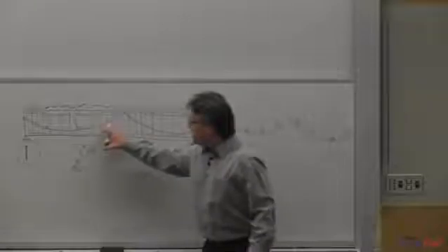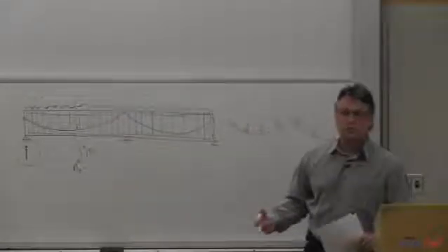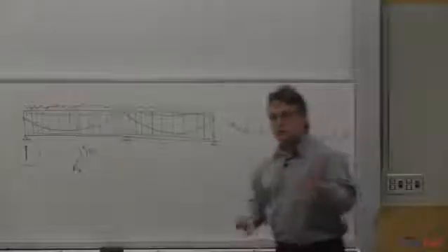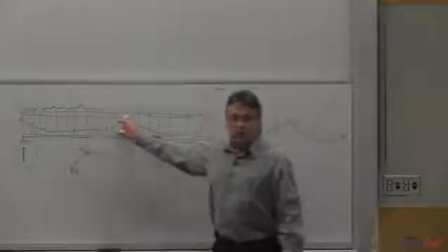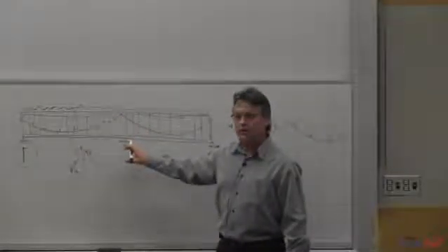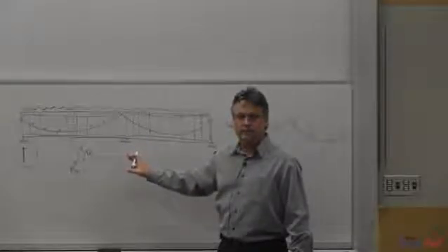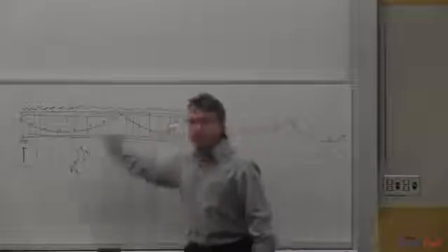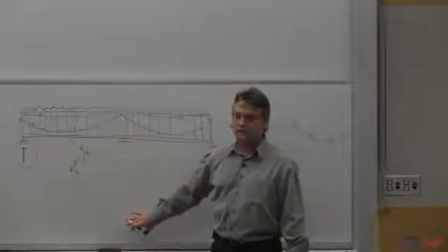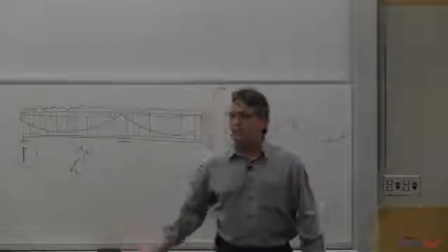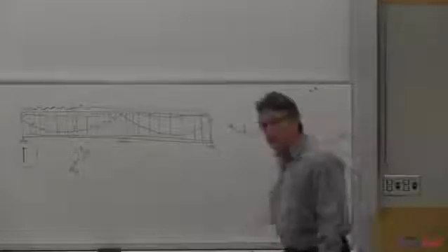Now in homework number 5 and number 4, we're back to putting on the applied loads. The applied loads are the only real loads in homework number 4. In homework number 5, the applied loads plus one other thing created real shears and moments. What was that one other thing? It wasn't just the applied loads that you used to come up with the demand moment. What else did you have to account for? The secondary effects. The secondary effects created real reactions, not fake concrete-only reactions.